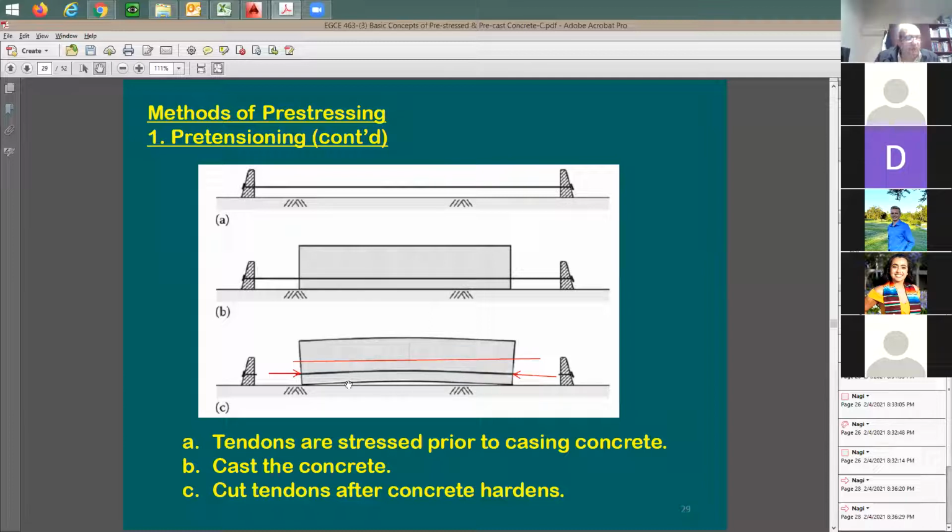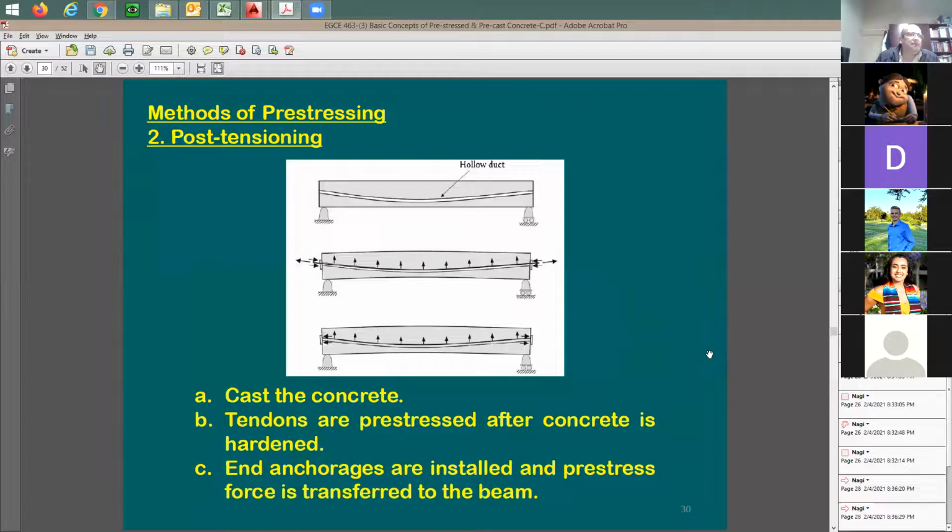This is why you don't really want to sit it in a flat area or flat bed. You'd like to have it on 2 supports. Because when you have it on 2 supports, guess what's going to happen? The self-weight of the structural member itself is going to be pushing it down. And this structural member is going to be almost flat. Does it make sense? Yes or no? Yeah. Okay. Yes. All right.